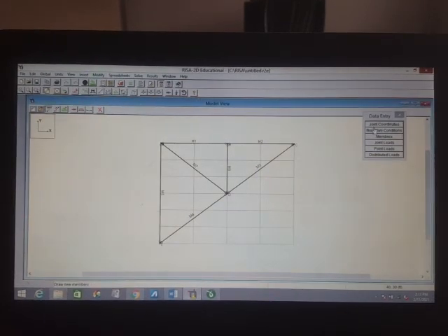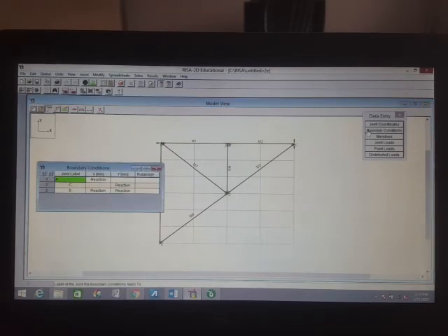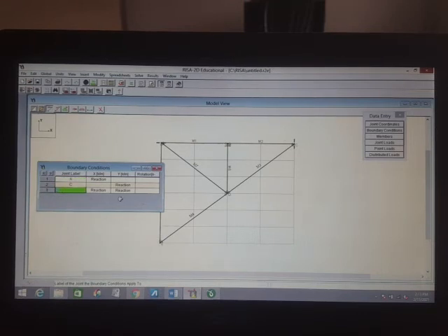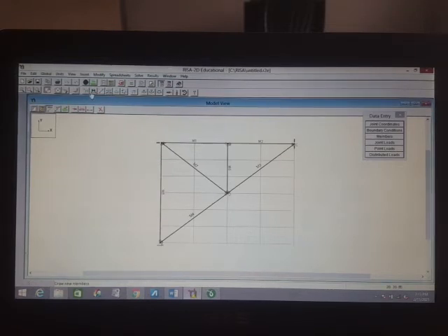By the way, what's the boundary conditions? Oh, sorry. This one should be letter E, joint E. Okay, so this is the label or the symbol for the roller support. That's along the X. The reaction is along the X. This one, the reaction is along the Y. It's a roller. And if it's a pin, then this is it.